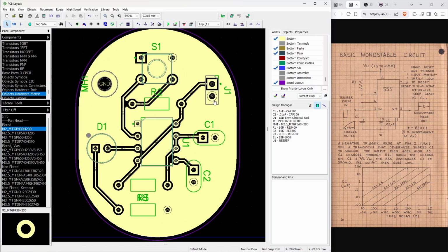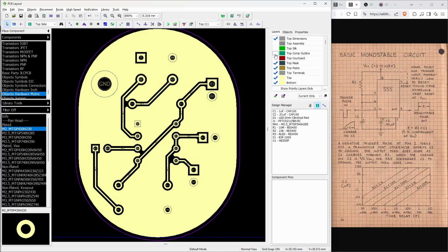One thing I might want to do, I've got all these ground connections, but those can be hard to solder by hand because there's a big pool of copper here. If we start removing some of the things here and only see the... wait, those are bottom. So what you can see at some point is that, yeah, this is what it would really look like, right? So it's just a hole with copper around it.